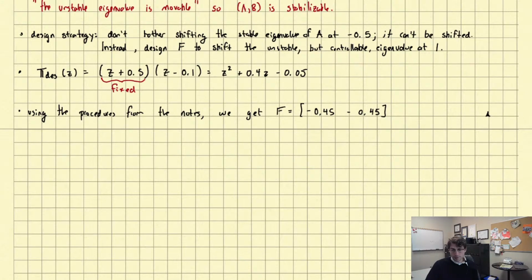Okay, so we have solved the stabilization problem by using this notion of controllability, right? So again, at the end of the day, if you do have sensors for all the state variables and you want to stabilize this equilibrium at x equal to 0, what you need at a minimum is that the pair AB be stabilizable. We have a test for doing that, right? So you can check whether or not it's possible and then design your F accordingly. If AB happen to be controllable, then not only can you solve the stabilization problem, but you can arbitrarily assign the eigenvalues of this closed loop system.